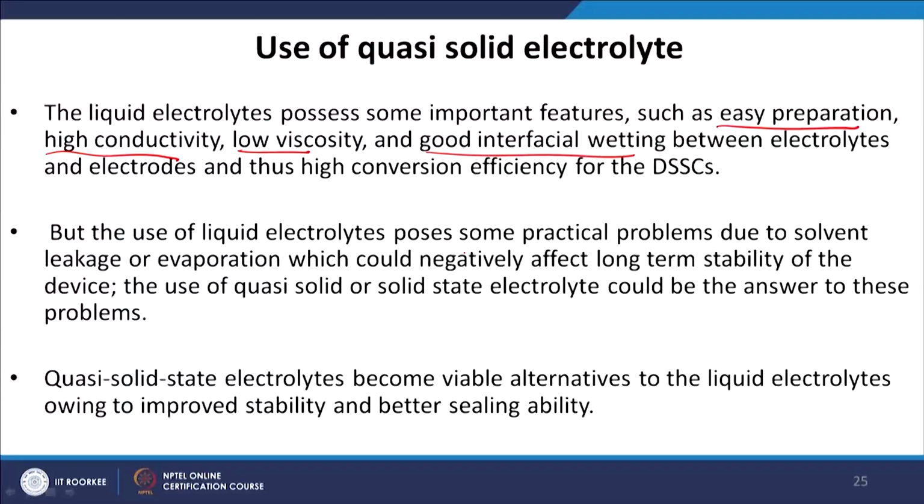But the use of liquid electrolytes poses some practical problems due to solvent leakage or evaporation, which could negatively affect the long term stability of the device. Now, these liquid electrolytes are volatile and corrosive. So, they evaporate over time. Let us say I put some drops of electrolyte in my device. If I do not seal it properly, after some time the electrolyte will evaporate. So, nothing is left in the device to regenerate the whole process. The electrolytes intrinsically show the property of volatility, and I cannot get rid of this. So, that is one of the major disadvantages or drawbacks of the liquid based electrolytes.